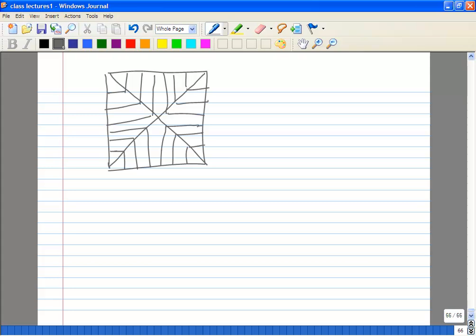Each one of these is a metal or poly strip, and each one of these lines is a slot. It's basically an empty space between adjacent metal strips. What will happen? Obviously there cannot be any eddy current flow, because now you have slotted it, you have created an open circuit.